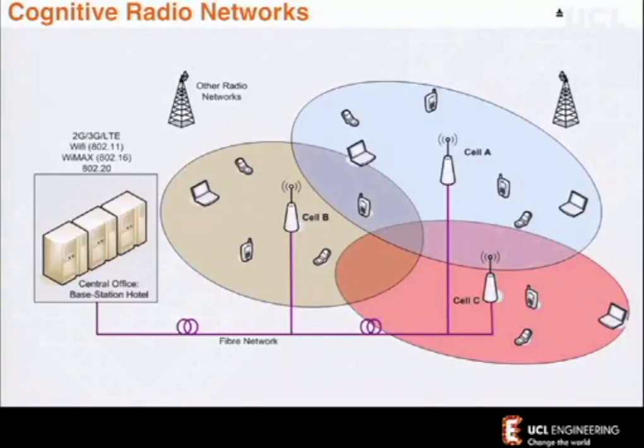Well, a lot of work has gone on in what's called cognitive radio. The idea of, can I sense the network and make decisions? Much of it is viewed around the idea that all of my terminals are pretty much ignorant of the rest of the network other than the little bit that they can see. Because in most situations, that's going to be the case. Except for the fact that if I'm taking a huge chunk of spectrum and transporting it back here for processing, actually, I could know an awful lot about the network, about the spectrum usage within my network. I could create almost a map of spectrum usage in real time if I'm taking a large enough chunk of spectrum.